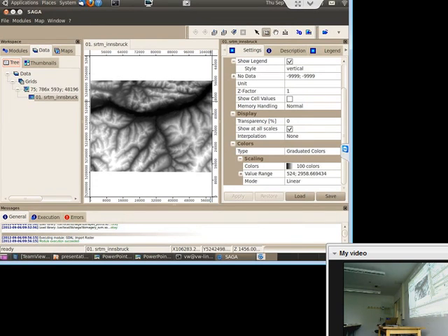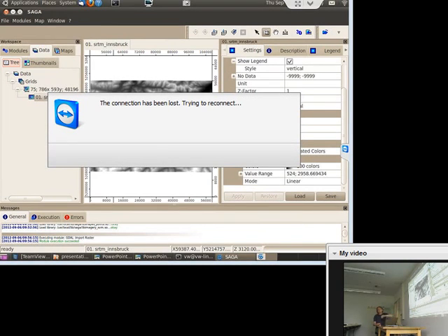Okay, so the first thing will be to use another palette, the SAGA default palette, to change from grayscale to the SAGA default palette. And this is simply done by opening up the color palette editor. Once you see the settings, you click into the field of the colors,